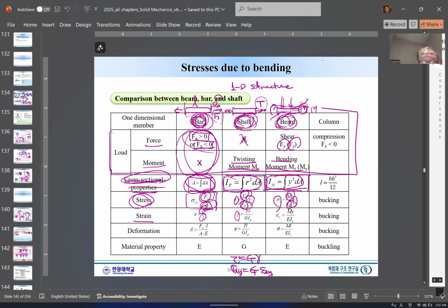So we have a G here for the shear strain. Sometimes gamma is given as twice epsilon xy, and we need to be careful about that one. But anyhow, we simply divide by G here, and divide by E here. And for deformation, how much will this delta be?